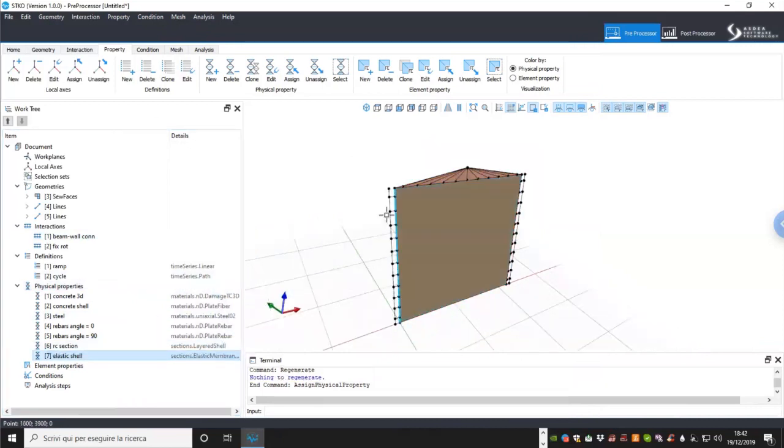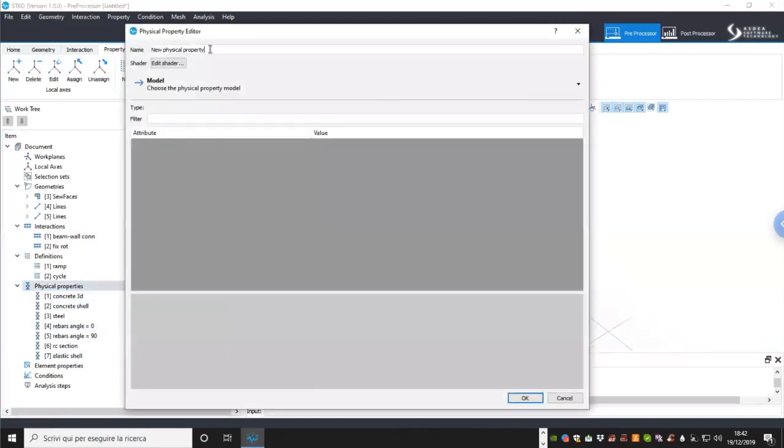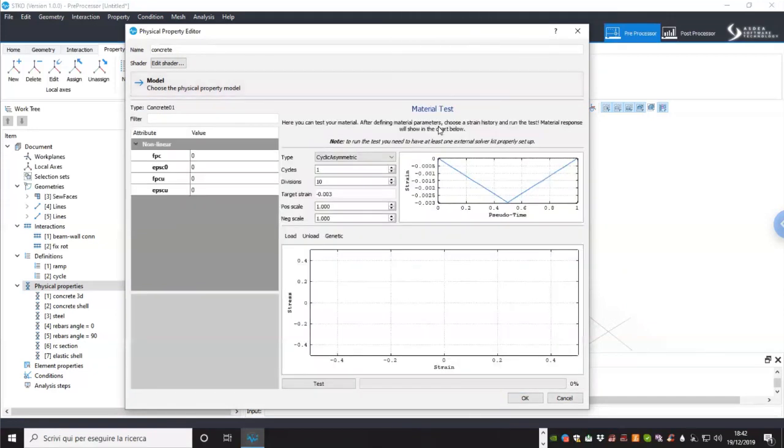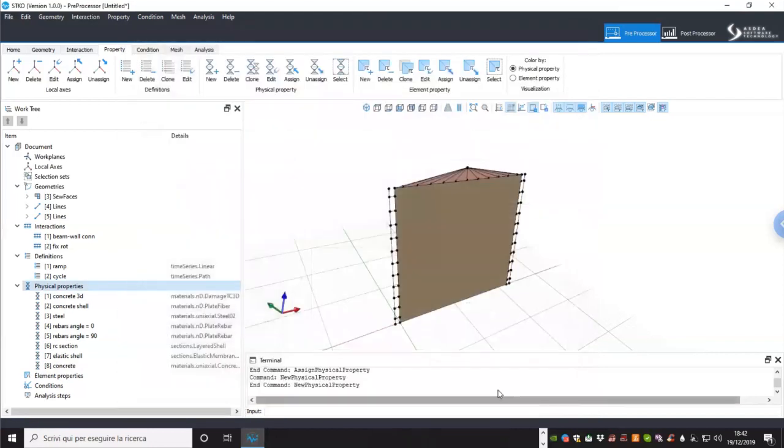Okay. Now we need to assign material properties to the beam. Now let me go quite fast here, and let me create a concrete uniaxial material, because we are going to create fiber section for the beams. Materials, uniaxial, concrete, 301. And we choose minus 28.7, minus 0.002, minus 5, and minus 0.1. Okay, now it is not so much important. We just need to create a cross-section.